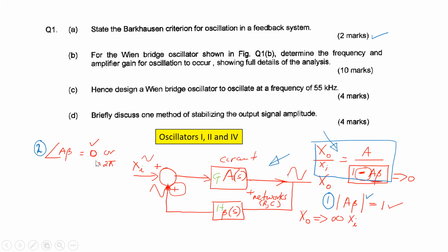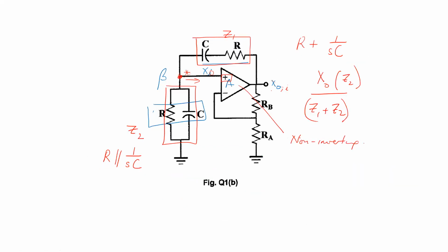All right. If this had been interchanged and I had a minus here and a plus, then whatever is the output here is going to be minus, right? It's going to be 180 degrees out of phase with whatever went in. In other words, it's going to be a minus. So we're not going to have the positive feedback inside of there, right?